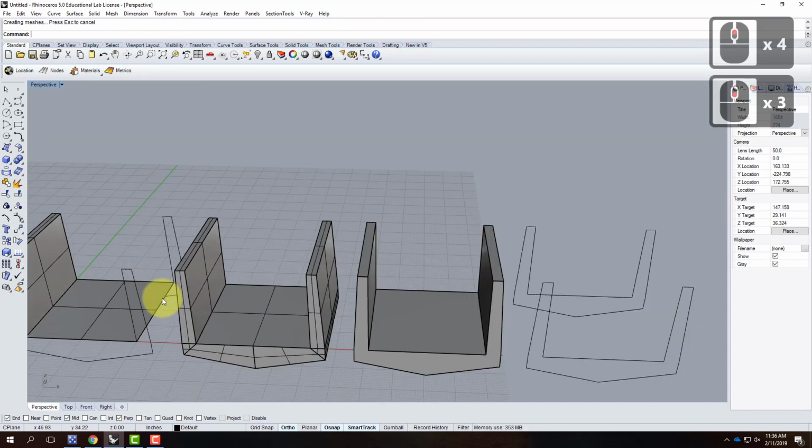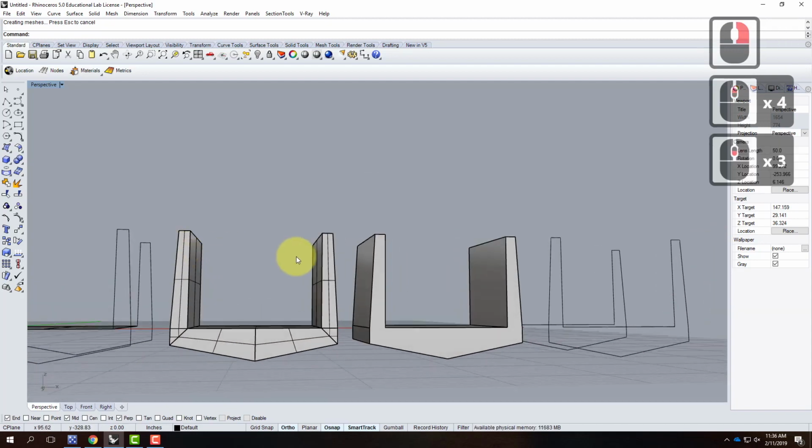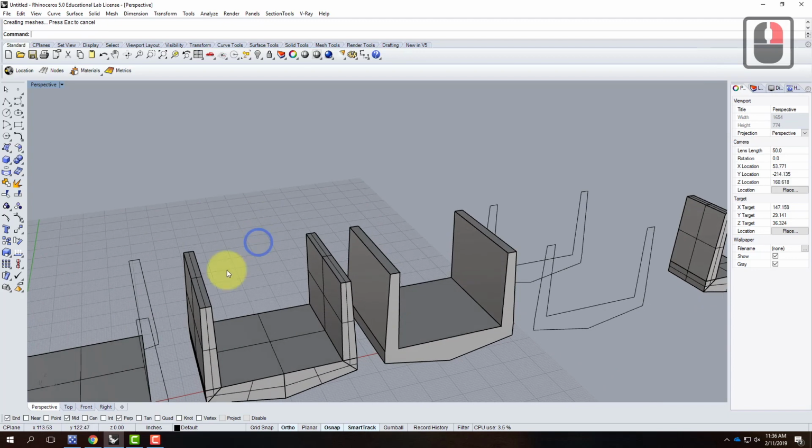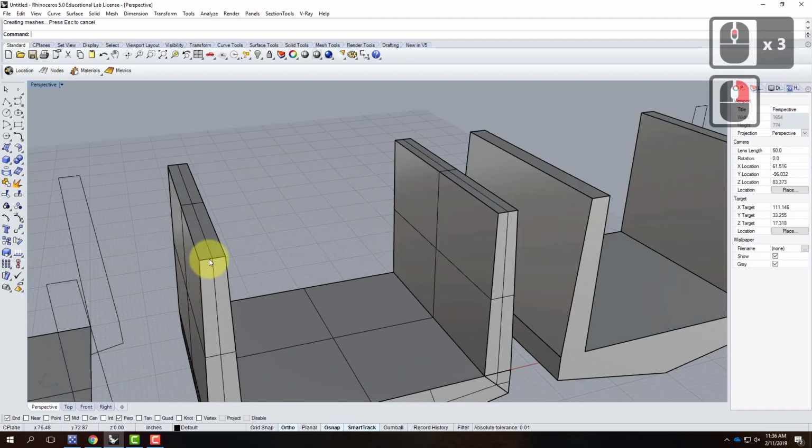OK, so now in a typical, I'm envisioning this as a little piece of concrete. And typically on the edges of concrete, when you're building a section like this, having a sharp edge is dangerous from a formwork standpoint because it has a tendency to break. And so if you look around at concrete, the benches out here are a perfect example. The edge isn't sharp. It has a chamfer on it. So we're going to create that same kind of a chamfer on this shape as well.